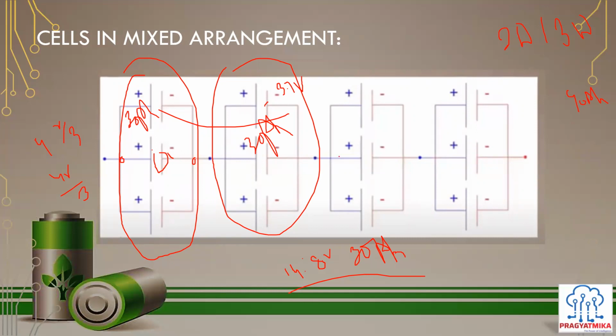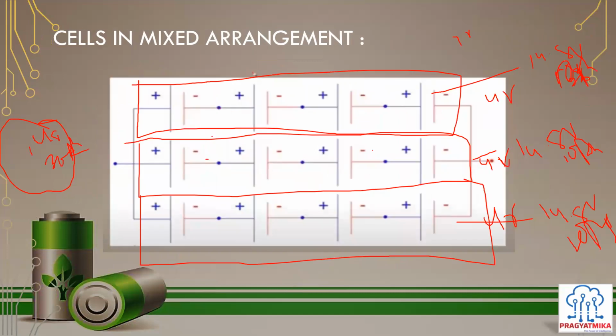Or maybe the total capacity of the pack would drop because one cell is not taking the full amount of current, but still we won't have any knowledge of which cell has gone bad. It is also possible that this cell gets open circuited, but there is no impact on the potential, because the other 2 have the same potential. Even if connections are made individually to each cell, this would be the case.